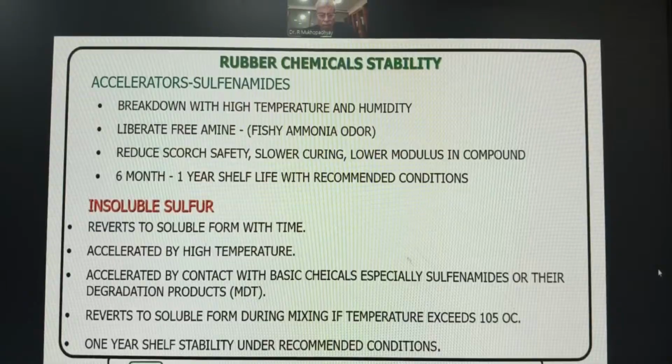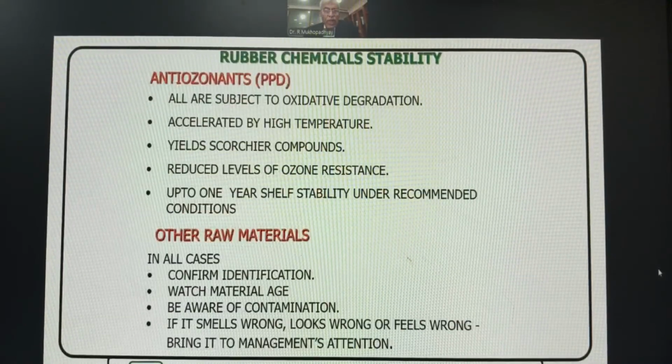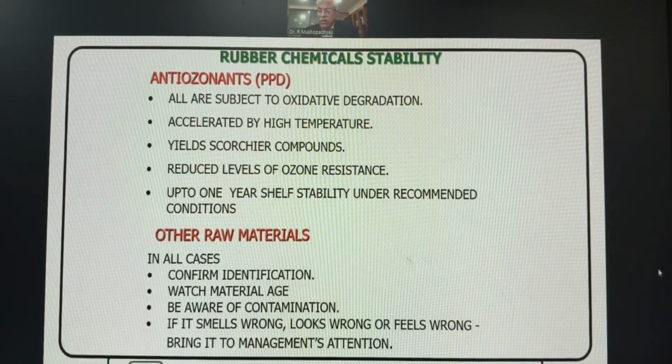Now the shelf life also, you have to consider. The sulfur is a maximum of 1 year in proper storage, with humidity about 60% and the temperature generally about 23 plus or minus 2 degrees centigrade. Similarly, the antioxidants are also subject to degradation.